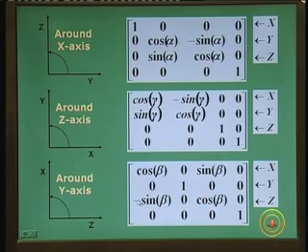I hope you play this around yourself with the whole thing again, which we talked about in the last 10 minutes, starting from the right hand coordinate system, talking about gripping the axis, and the thumb pointing upwards to the positive direction, the fingers pointing to the positive direction of the rotation, or looking down to the origin with counterclockwise convention of positive rotations. To maintain that consistency with respect to all the axes, you need to have one of the signs reversed for the rotation matrix.